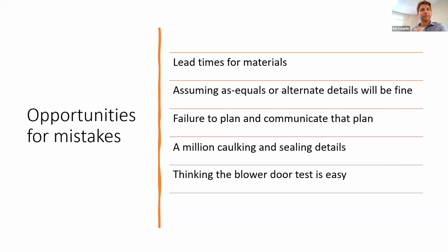And then the last one is thinking the blower door test is easy is a big mistake. Our superintendents kind of said, oh, okay, you just seal everything up. And then at the end of the job, we'll do it. The subs think that, to a certain extent, the owner thought that. Our architect kept saying, be careful. And so I'll talk a little later about some specific things to do with the blower door test.